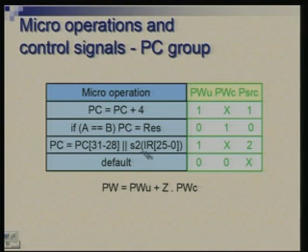So, to make this happen, we need to make the unconditional write signal 1, we do not care what PWC is, because when PWU is 1, the values here do not matter, the result is going to be 1. It is a sort of overriding signal. But on the other hand, when we want to activate PWC, we have to make sure that this is 0, because this will otherwise suppress that.